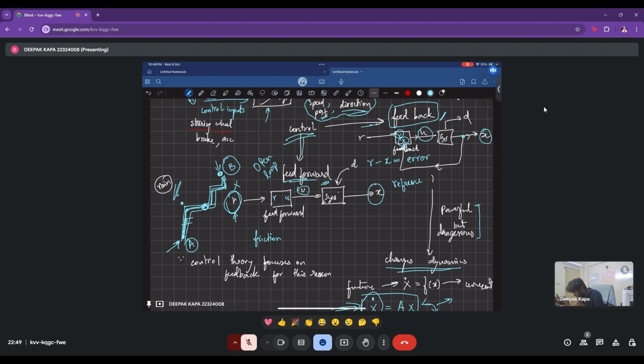So say I want to go from point A to B. My feed forward controller is going to tell my car to go 50 meters straight, then take a right, then go 50 meters again, take a left, take a right, and take a left again. So at one go, I just told my system to do everything. This feed forward controller does not have any reference to the states of the system. It does not know what the system's actually doing at a certain point of time, but just gives the system all the inputs it requires to reach the final destination.